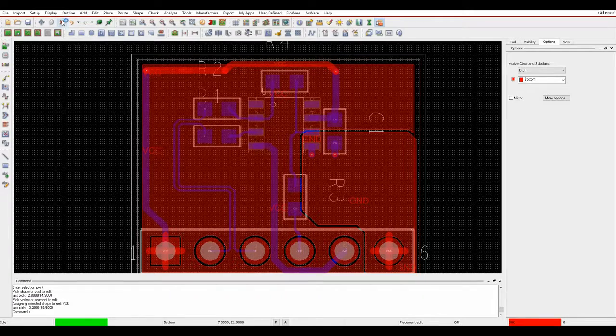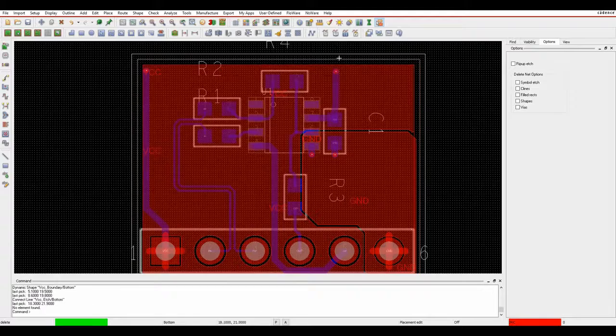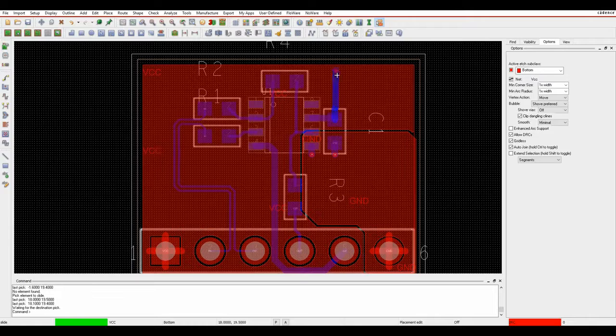and you can see that effectively that net gets consumed. So we don't need to route this trace, because obviously we've got a via making connection there, and we don't need that one there, that's got the thermal relief, so we can actually get rid of the via there as well. And worst comes to the worst, what we could do is always slide this via down, which tidies it up, so we've now got a VCC plane and a ground plane.